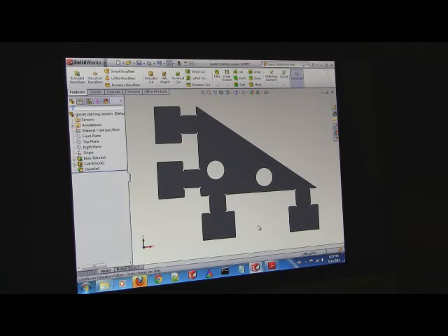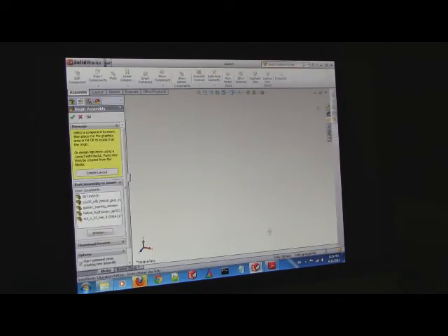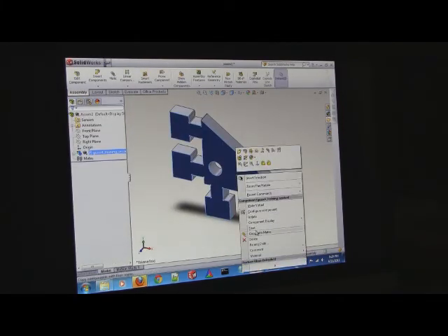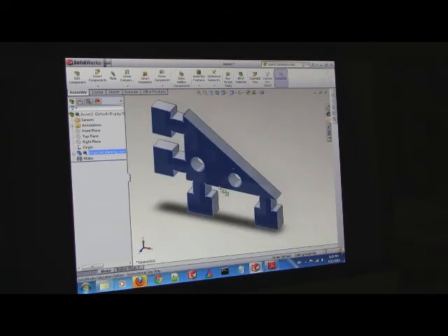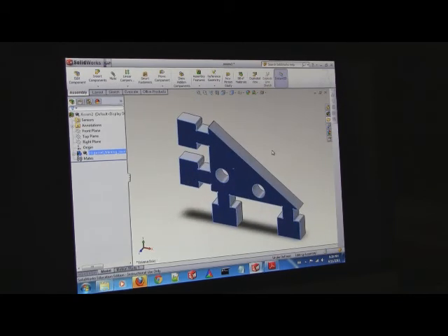I hope so. Okay, so let's make an assembly. Press File, New, Assembly. Take that gusset that you just made. Insert it here. Float it. And I'm not going to proceed until everyone has a gusset that's floating around their screen like a ghoul.